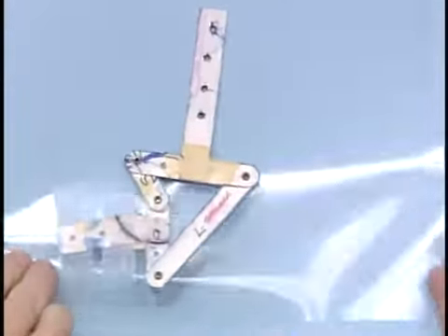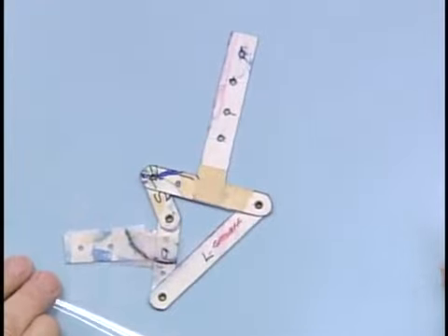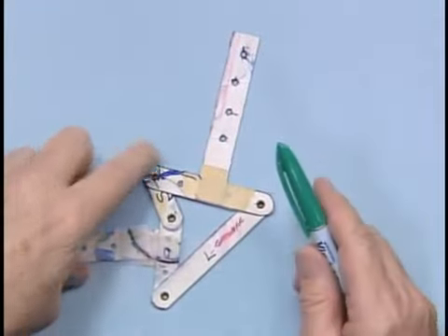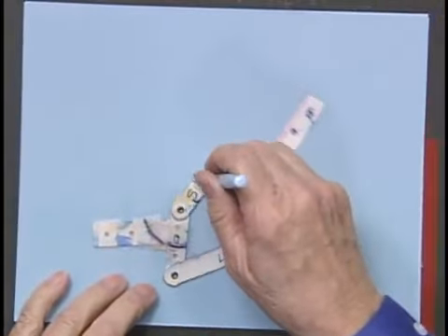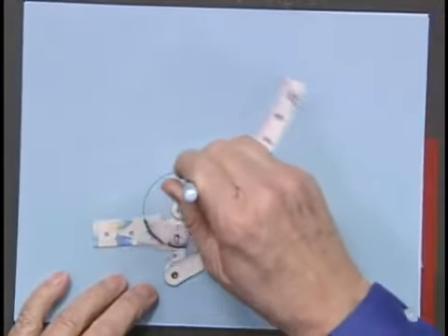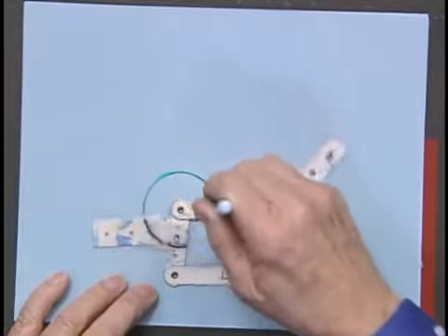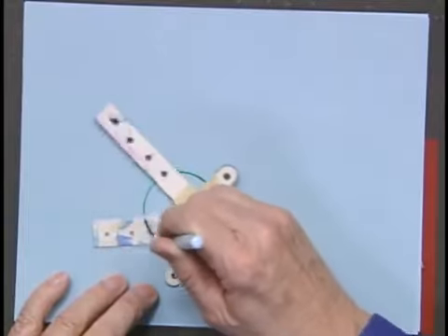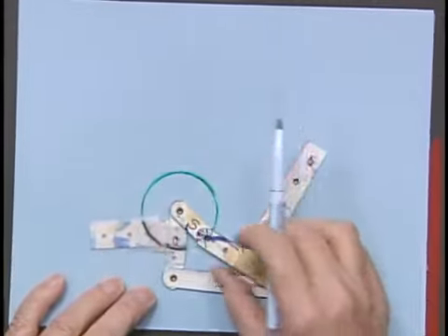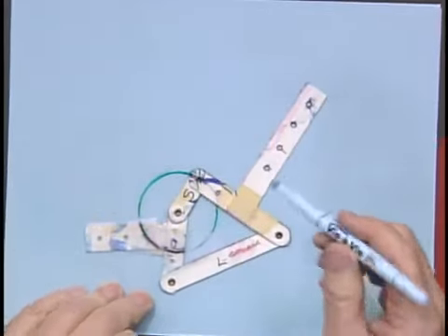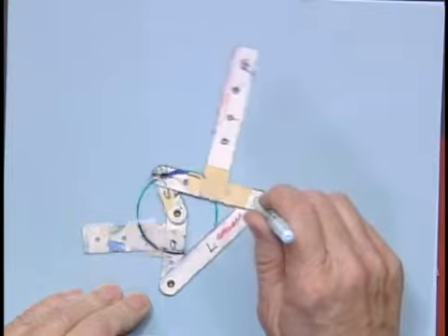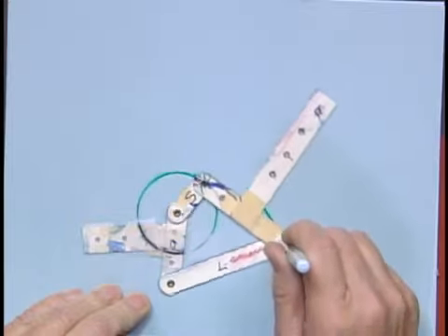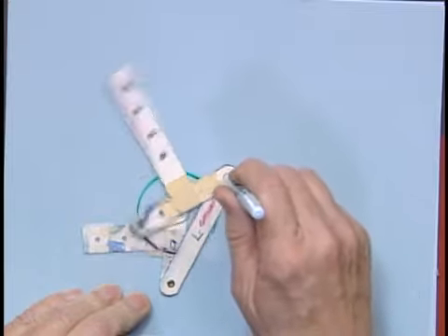I don't have quite as large a coupler on this, so it makes it a little bit easier to see. I don't hide so much of the curve, but just to, again, prove to you that this is in fact Grashof, I'll make that go around in a complete circle. If you've seen the Grashof tape, then you know all about that. And by that same token, this point over here, which is instance center 3, 4, if I backdrive the linkage from the rocker,